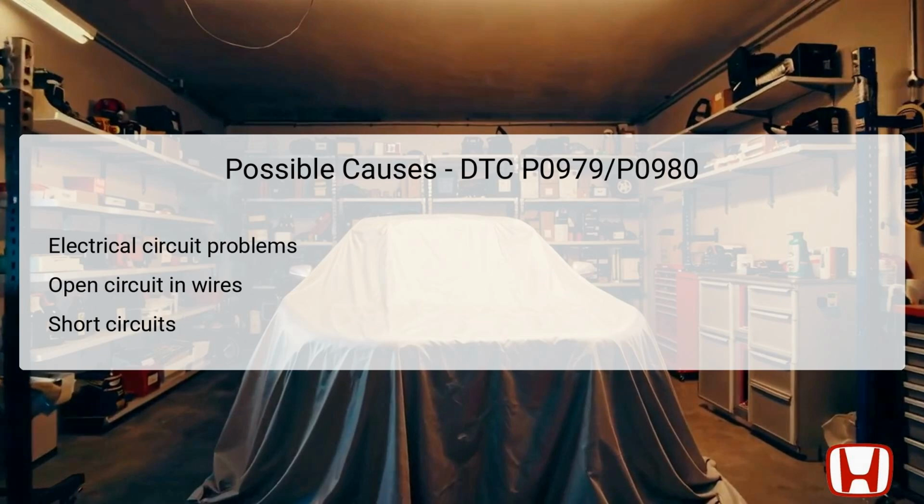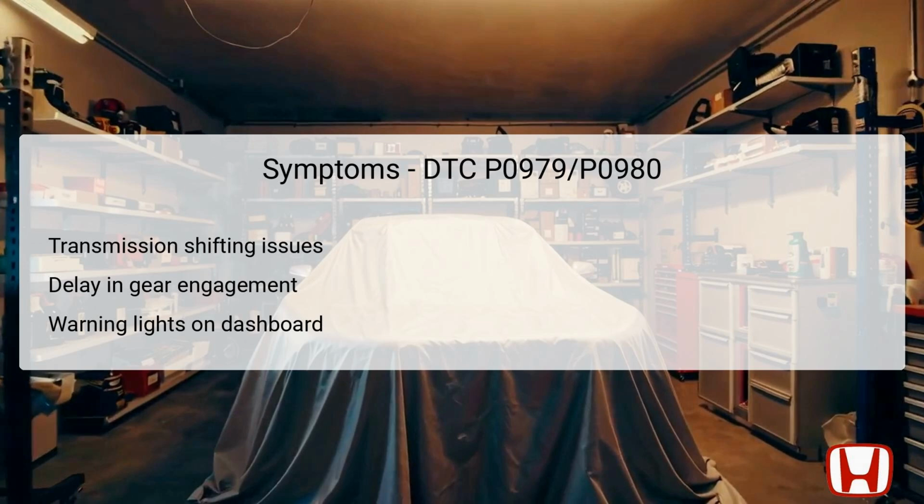Symptoms relating to DTC P0979 and P0980 often manifest during operation of the Honda Pilot. Drivers may notice transmission shifting issues, where gears do not engage smoothly or shift as intended. This could also result in delays in gear engagement, which could be confusing and harmful to the overall driving experience.